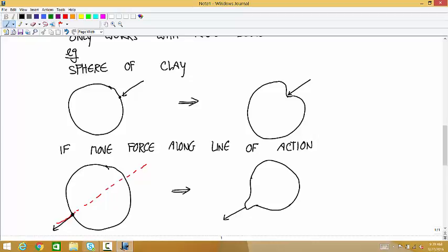Doesn't the position of the force matter in a rigid body? It doesn't. Well, in some ways it does, but you can move the location of the force along that line of action, and it doesn't change anything. You can't move it anywhere, but you can move it along its line of action. So I'll do an example that shows. But couldn't you, in theory, move that force along its line of action so that it's not even contacting the object? Yes, you can. Yep, and you'd get the same answers.